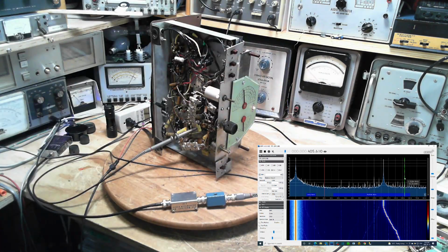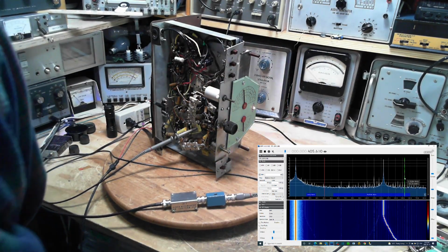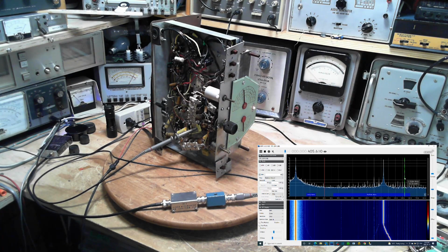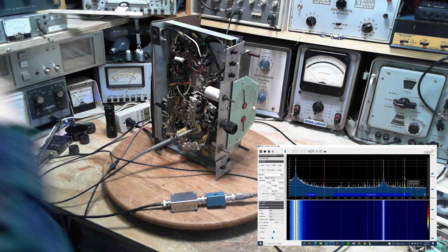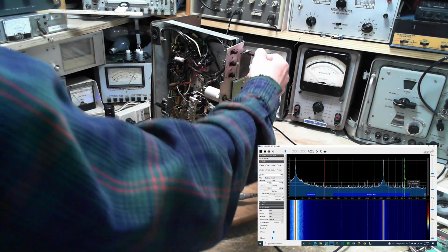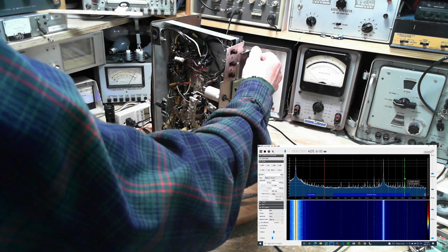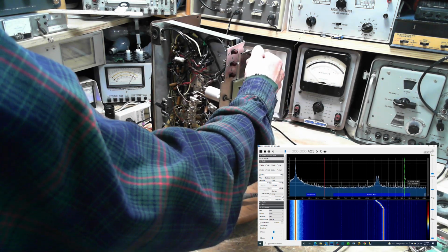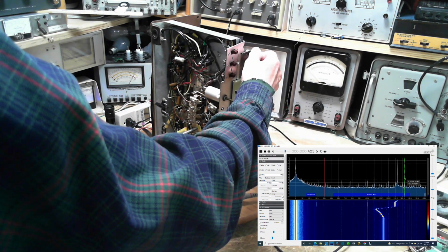So that means inside the radio right now, the local oscillator where it is, there is a signal being converted down to 125 kilohertz and being presented to the IF. But the IF is not interested in that signal. The IF is only interested in 455 and thereabouts. Let's go the other way now. We'll get the same signal back in the middle of the IF.